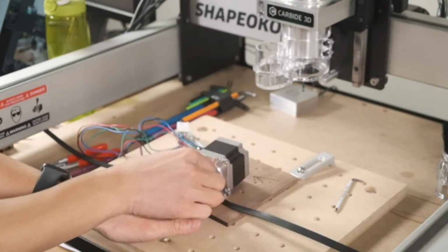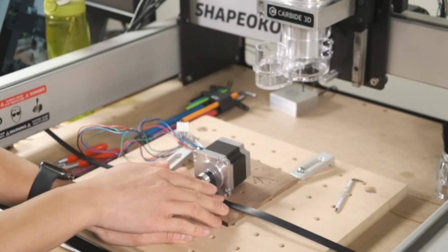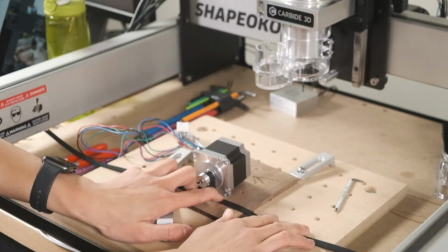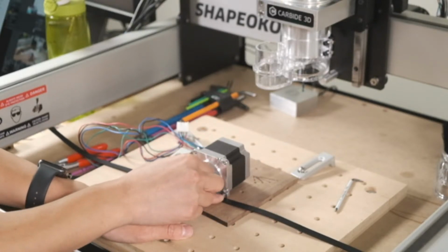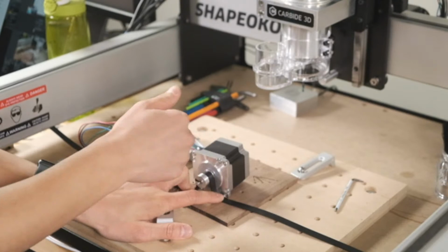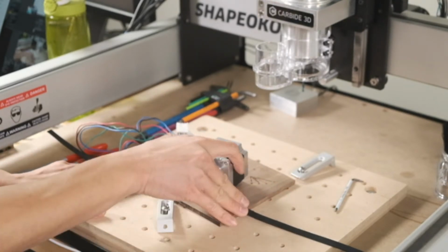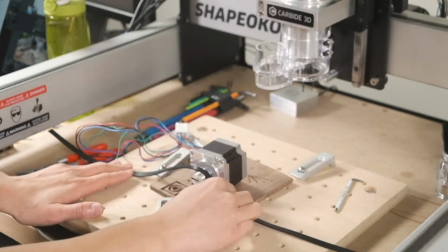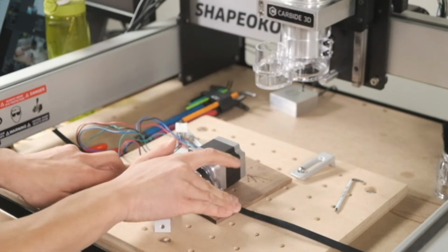Now, that will make sure your machine moves when this rotates. But there are some other things that could happen if this isn't perfectly tight, which is you might get backlash. If you think about the stepper motor as pulling its way along, if you have a little bit of slack on one end, what's going to happen when the motor tries to move in this direction is it's going to start pulling up slack until it's tight, and then it'll start moving.